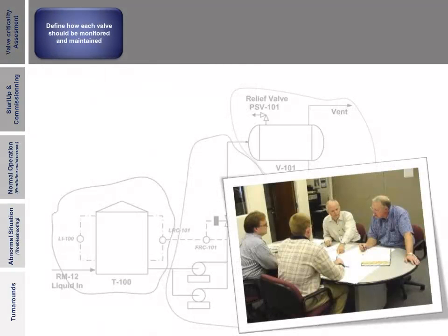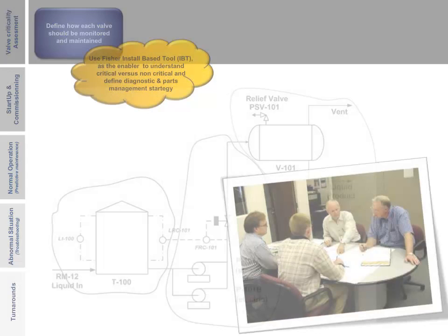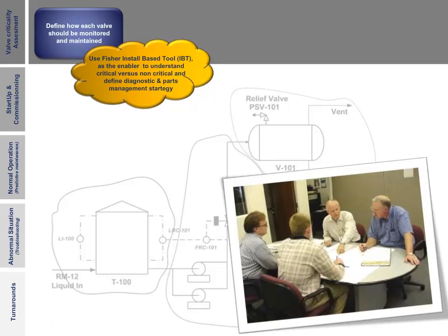All control valves in plants are not equal. During the first phase, you should assess the criticality of each control valve to determine how they should be monitored and maintained. Use the Fisher Installed Base Tool, IBT, as an enabler to understand critical versus non-critical and define diagnostic and spare parts management strategy.